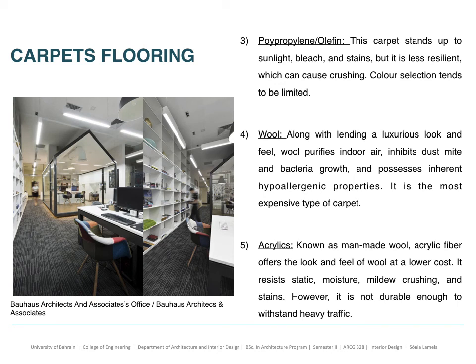Then the wool, the natural one, along with lending a luxurious look and feel, also purifies the indoor air, inhibits dust mite and bacteria growth, and possesses inherent hypoallergenic properties. It's the most expensive type of carpet that we know. And to finish, the fifth one is the acrylic. It's known as a kind of man-made wool. It's acrylic fiber that offers the look and feel of wool at a lower cost. It resists static, moisture, mildew, crushing, and stains. It's not, however, as durable as normal wool in withstanding heavy traffic.